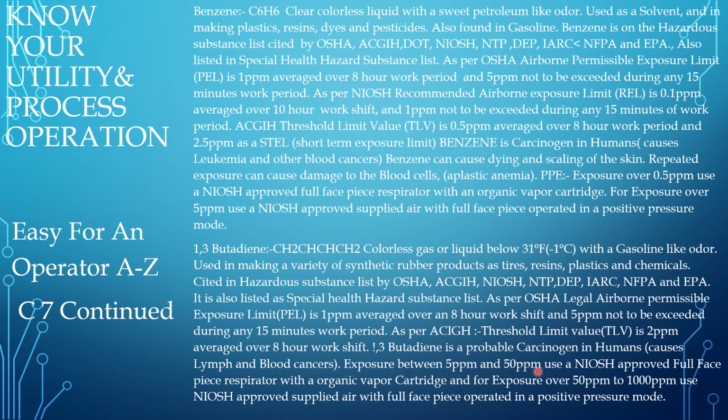For exposure between 5 ppm and 50 ppm, use a NIOSH approved full face respirator with an organic vapor cartridge. And for exposure over 50 ppm up to 1000 ppm, use a NIOSH approved supplied air full face respirator operated in a positive pressure mode.